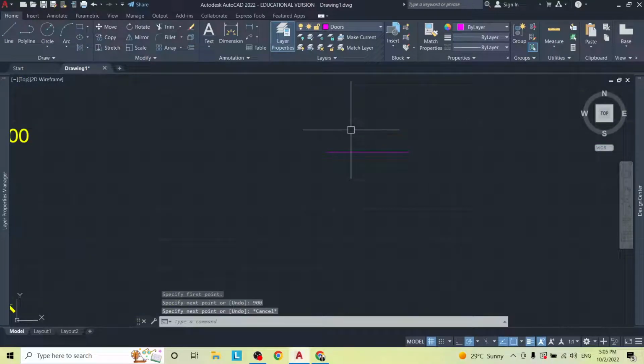Okay, so what we need when we are doing a door frame, we're going to show the door. If you look at the door, it's not just a door attached to the wall. There's a door attached to a piece of wood. We're going to draw that piece of wood. So the internal space of the door is going to be 900 millimeters, and that piece of wood is going to be on the outside of that 900 millimeters. That piece of wood is typically maybe 1 inch by 4 inches. So we're going to basically show that looking down on the door.